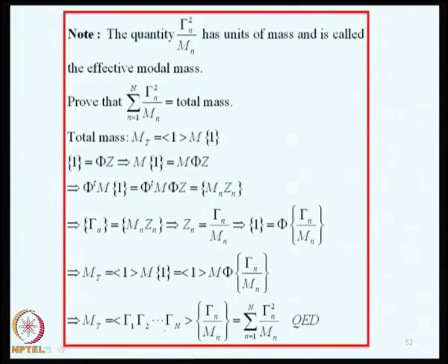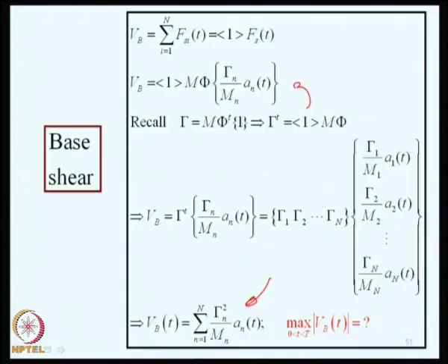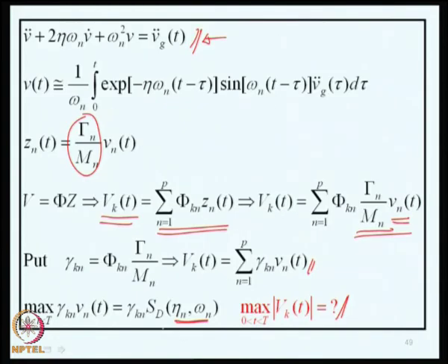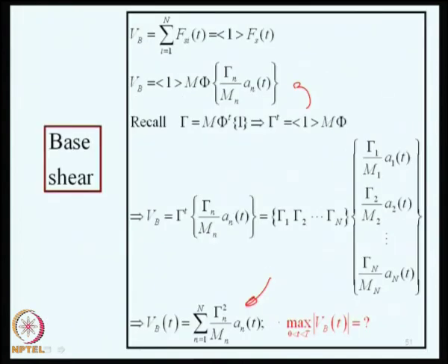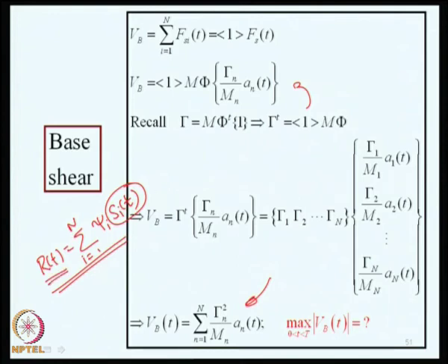So, for each of these quantities, displacement or spring force or the base shear, we are getting a general form of the expression, say, response R of t is some kind of summation, i equal to 1 to n, of some psi i into some Si of t. This is a generic form we are getting. The maximum value of Si of t can be estimated based on the given response spectra, but it does not tell us what is the maximum value of R of t. So, that is a general question that we are coming across for each of the situations.